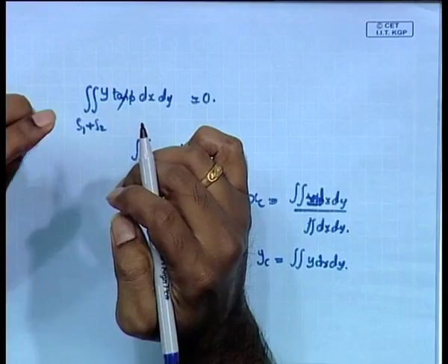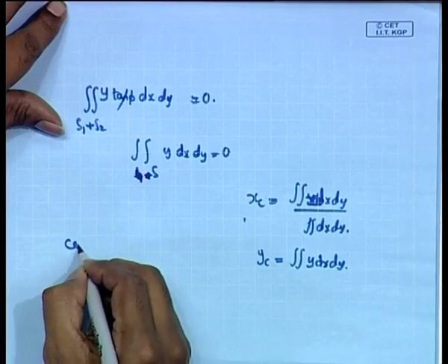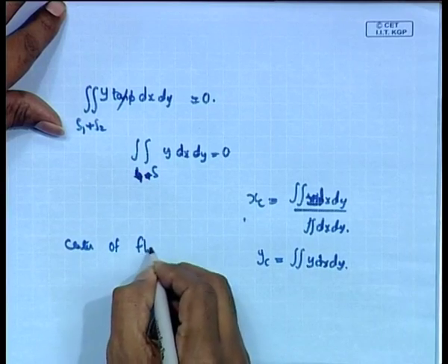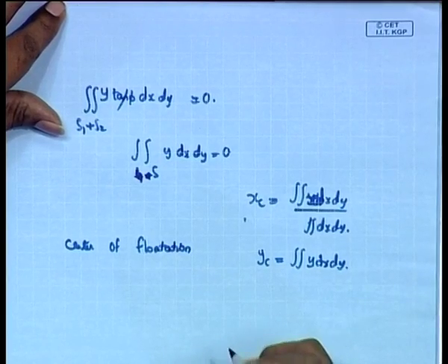water plane area. The centroid of the water plane area in the case of a ship is known as the center of flotation, and therefore, we can say that the body inclines about the center of flotation. So, the axis of inclination, if you assume it to be the longitudinal axis, will be passing through the center of flotation. This makes an assumption that the angle of inclination is very small.